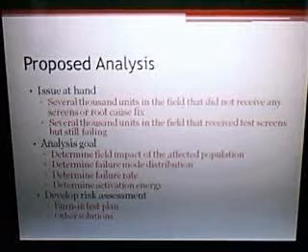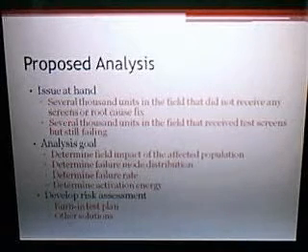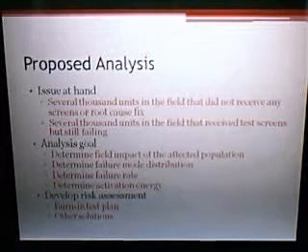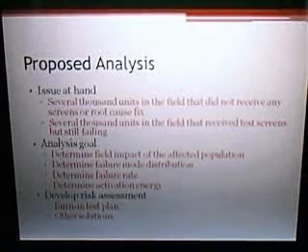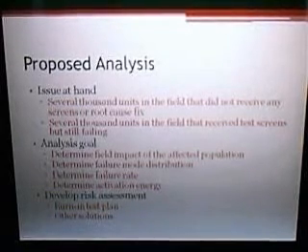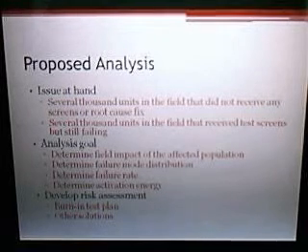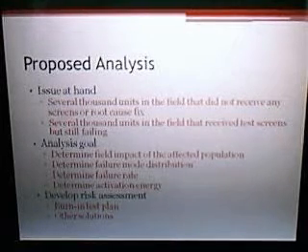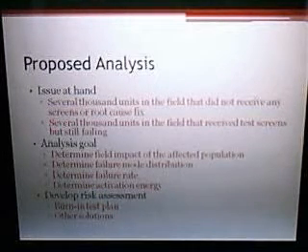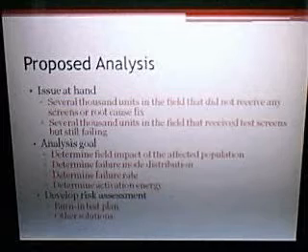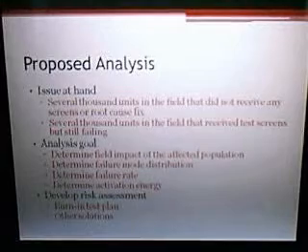So it's appropriate for us to start our analysis by looking at the field impact of the affected population, looking at the failure mode distribution, determining the failure rate, and also determining the activation energy, which will all lead us to coming to conclusions in terms of proper test procedures along with handling of parts in the field. Again, the goal of this risk assessment that we will be performing is to determine the burn-in test plan and other solutions.